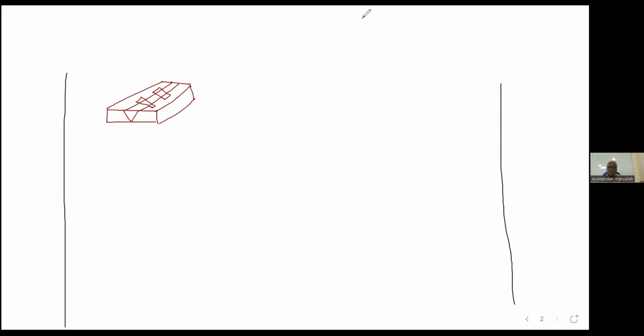Now, if you have a pipe weld, for example, this is your pipe weld. Again, 2 test coupons. One should be cut at the top, another at the bottom. If you take the circle shape, this is your weld. So one specimen here, one specimen here. 2 tensile tests are mandatory for procedure qualification. These are very important for the exam.